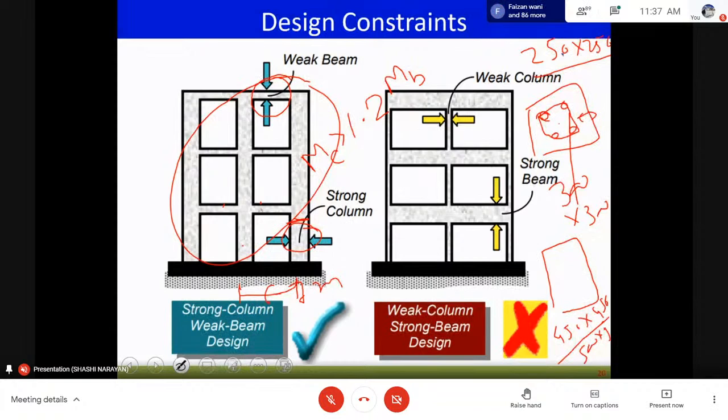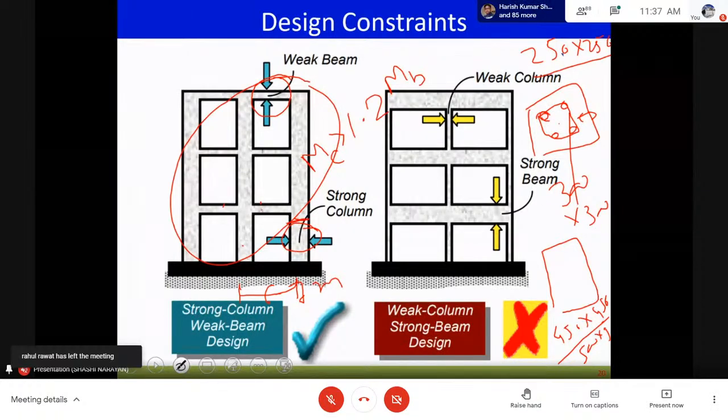If the architectural design is such that we are not getting this 6 to 7 meters, and 6 to 7 meters is generally 18 to 20 feet, generally the room sizes we have are 10 by 10 or 12 by 12. So instead of having a column in between the two rooms, it is better to have columns at the ends only. That is also one way in which we can go with the design for earthquake resistance.